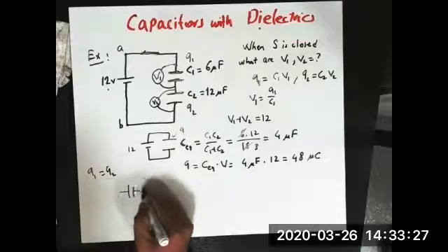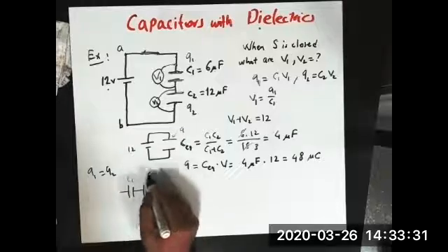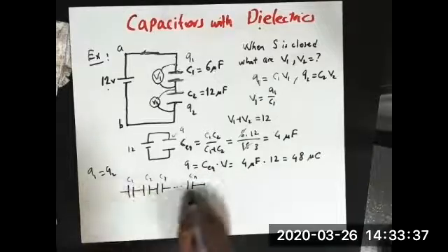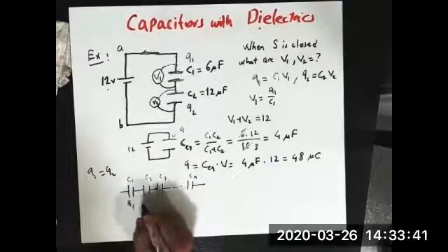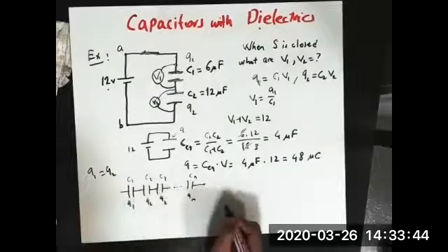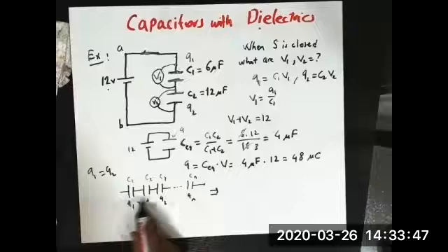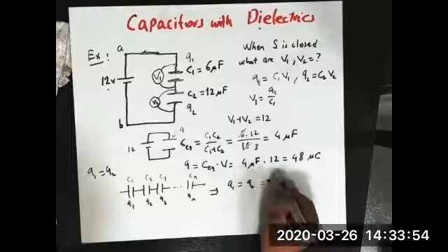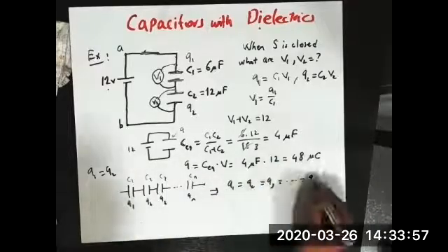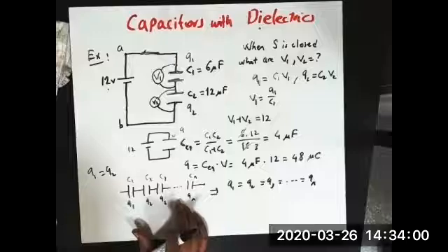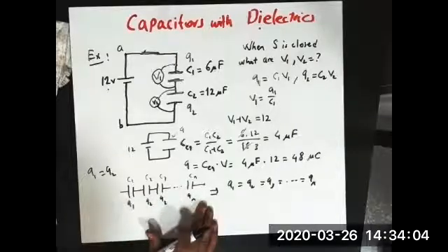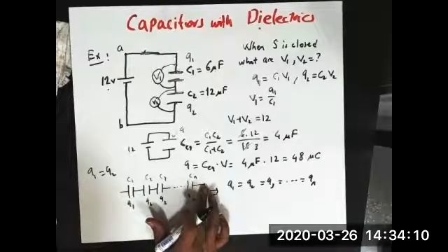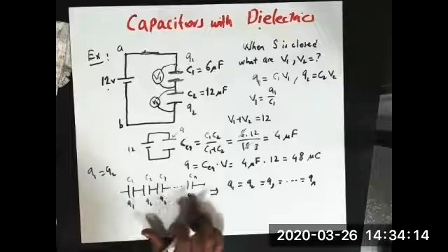If you have many different capacitors, C1, C2, C3, etc., Cn, which are serially connected to each other, obviously you will say that this one will have Q1 charge, Q2 charge, Q3 charge, Qn charge. And I say that if all these capacitors are serially connected to each other, all the charges will be equal to each other. In electrostatic equilibrium, since there is no change in the current, if there is no current flowing between these capacitors, then all charges must be equal to each other, right?